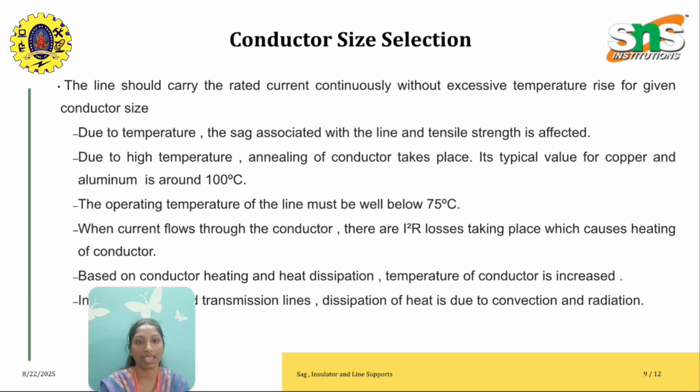All the rain or moisture content gets deposited on the transmission line, which creates weight. The conductor itself has some weight, which, as the days go on, will create a U-shaped structure. During the winter season, moisture content is deposited on the transmission line. Due to its weight, the conductor becomes U-shaped, which we call sag.